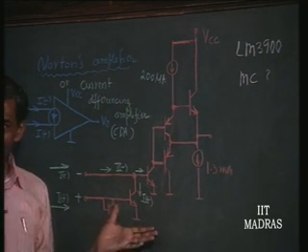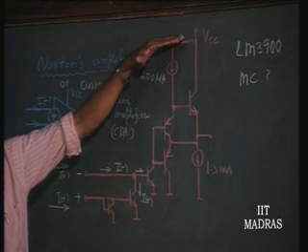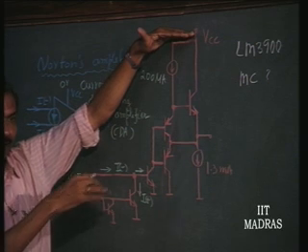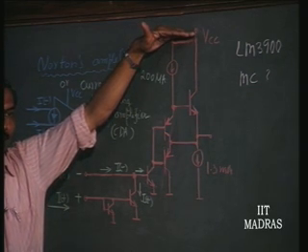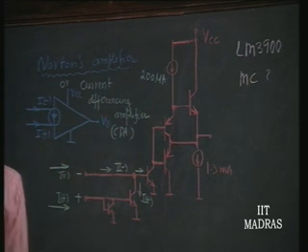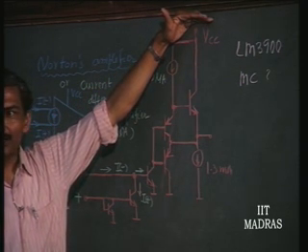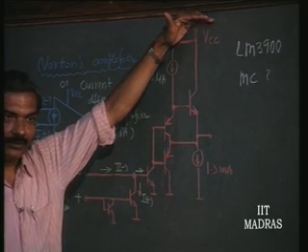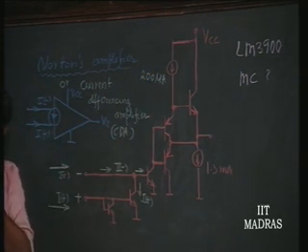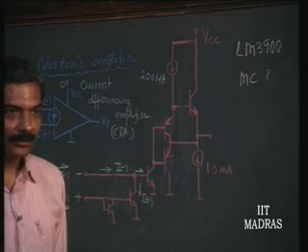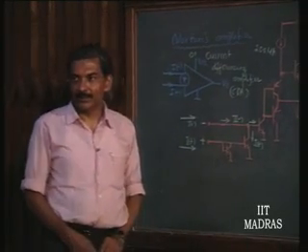The advantage of this over 741 is this: both these Motorola and National Semiconductor op amps have this advantage, that because it is current gain that you are ultimately after, the performance of this open loop gain etc. is going to be independent of power supply. And the power supply can range from pretty low values, maybe say 5 to 6 volts, to a 20 to 24 volts range. For the entire range you can use this without its parameters changing much, and use a single supply. Therefore, this is the cheapest amplifier available for most of the single supply applications,